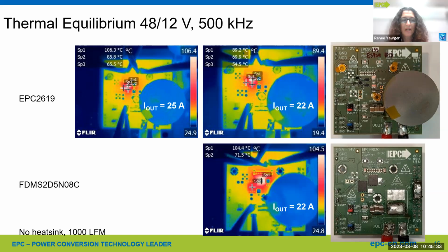Okay. GaN have small capacitors, so can the majority of MOSFET drivers be used, or do we have to be careful about that? Well, that's an advantage. I would say there's no problem in using a higher output driver if the concern is just the output. So yes, we have very small capacitance. What that means, and that's what I was showing in the slides for the Gen 6, is you have less gate driver losses. So that's very good for the gate driver. You might be able to use a smaller output gate driver basically.